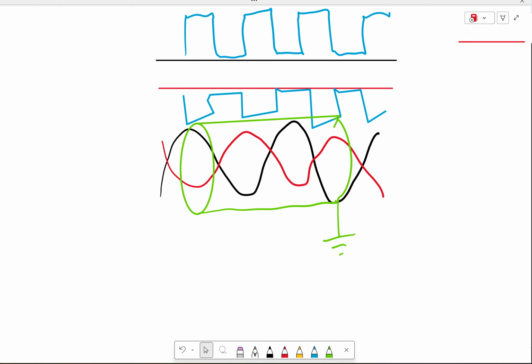When it comes to your CANBUS system, it's very normal to see twisted pairs of wires. If you have to depin a connector and do any work on it, it's important that you make sure those data wires, your CANBUS, are twisted back up. We don't want to leave it untwisted because that means it's more susceptible to interference. So if you see a conductor that's got a huge portion of the CAN bus hanging out and it's not twisted, and you're having interference issues and corrupt data issues, that might be something to look at.